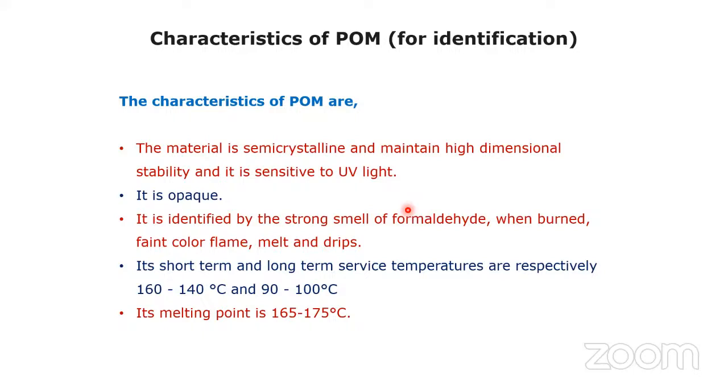Any example of short term? Suppose you have caps on a reactor, which you generally replace within a month, or within 15 days. If in some reactor there is a compulsion to use caps of this material, or a requirement of 150 degrees Celsius temperature, then for a short time you can use it, and after 15 days or a month you can replace it.